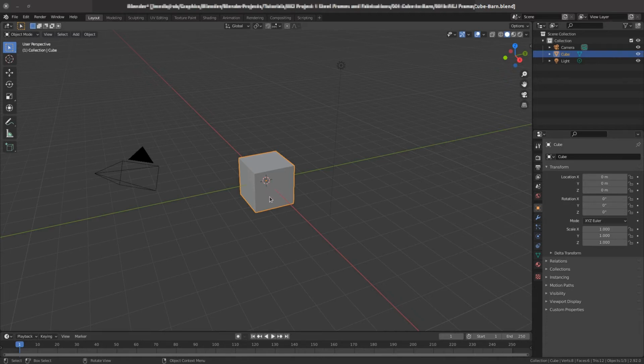So the first thing we need to do is turn the cube into a shape that represents a rolled steel joist, RSJ. If you watched the previous video where we made a reference image, you'd see I took some photos of my hand in front of two sides of the RSJ, so I've got a rough size reference between the two. Measuring back from those images, the RSJ has a ratio of 1 to 0.655 between the two sides.